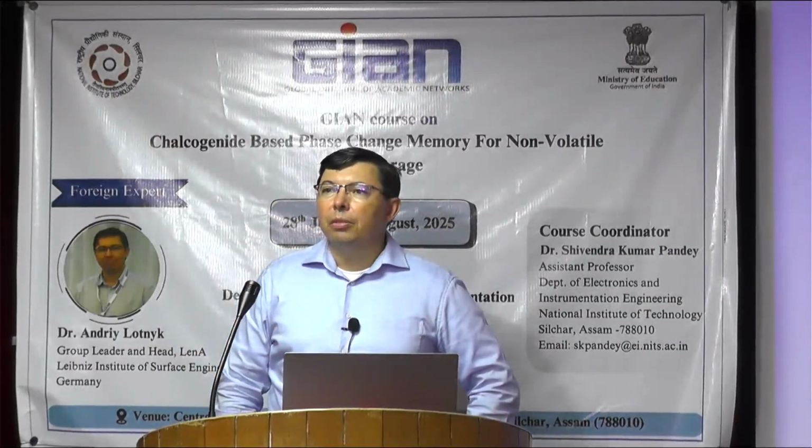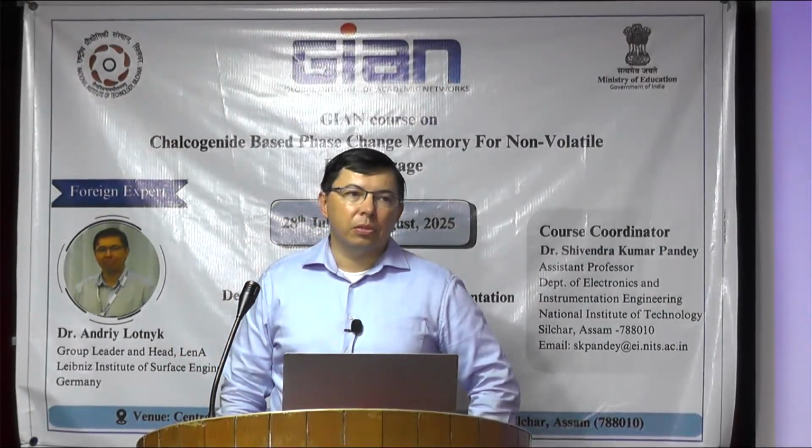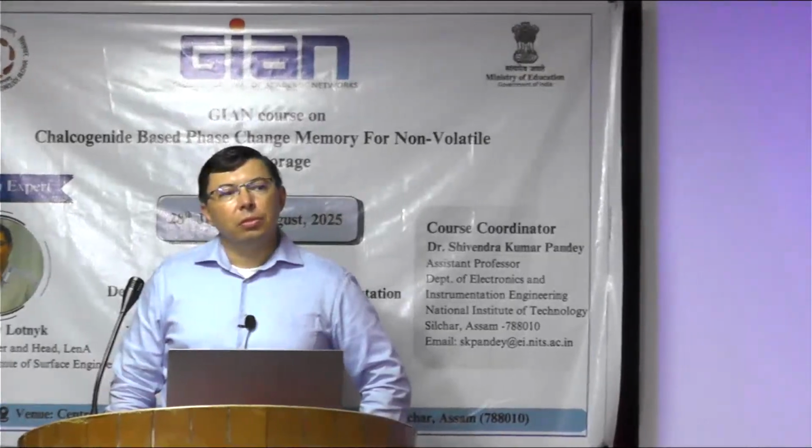Okay, so for the time being you are taking the sample from your system and then you are keeping it. So in between there is enough time to get oxides. So in the chamber itself, if you just cap, some capping materials are there, and later on there are some liquid processes, you can take it out and then characterize. We are using two thermal evaporations for deposition actually. So after one deposition is done, we need to take it down. That's the concern actually. Okay, fine.